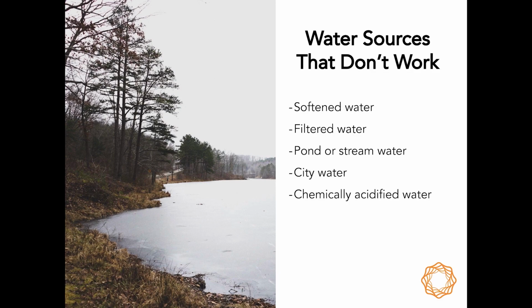Well, it's usually not. And not always. There are cases where it is okay. If it's coming from snowmelt or something like that, it's usually fine. But it is also very common for water, as it moves through the ground and through bedrock and then emerges in springs and comes into streams, it's not uncommon for that water to pick up a lot of carbonates and bicarbonates from the rock that it has filtered through as well. City water should be an obvious no-no because of the chlorines, the chloramines, and whatever various compounds it contains as antimicrobials.